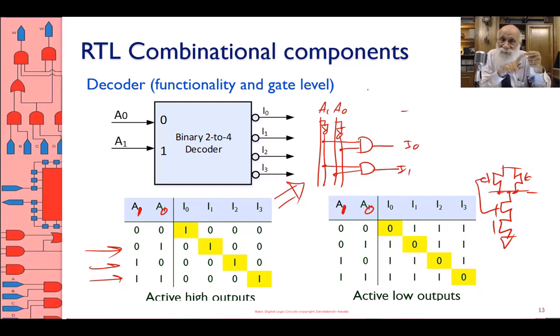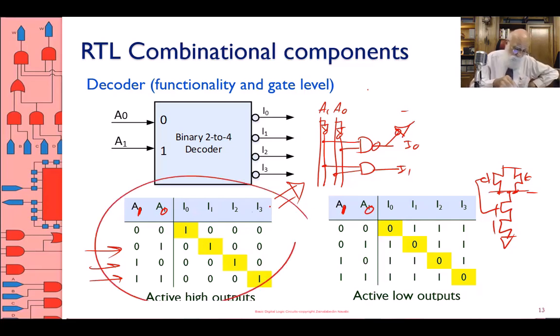That's not good, because if I put an inverter on the output, that gives me 2 more transistors. That gives me more delay. Okay, I can do that. I can put an AND here and put an inverter here, and therefore I will have the table shown on the left, lower left-hand side.